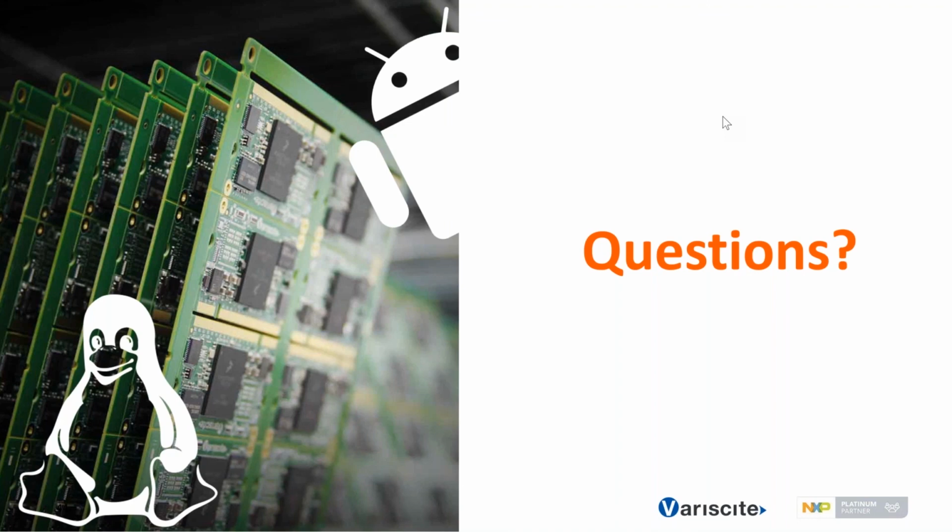Do you have any recommendations on how to reduce the Yocto Linux startup time? How low timings could we achieve? Let's say that the initial tuning is not that critical. The first point is always to remove all of the prints that you have on your console because they are time consuming. This will usually reduce the time by about 5 seconds. You have some timeouts in the U-Boot that you can remove. Then you need to start the real hard optimization.